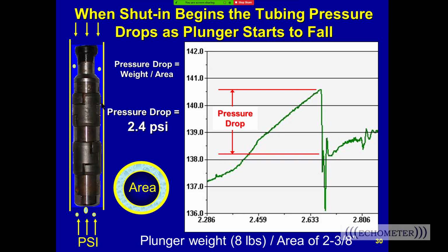I have a question from Anil Yoshi that I'm guessing is related to the plunger lift system as a whole. It says, is it possible for deviated wells? Usually with plunger lift, you don't run the plunger past about 60 degrees, maybe 40 degrees, because the plunger won't come back up if you run it out too deep.